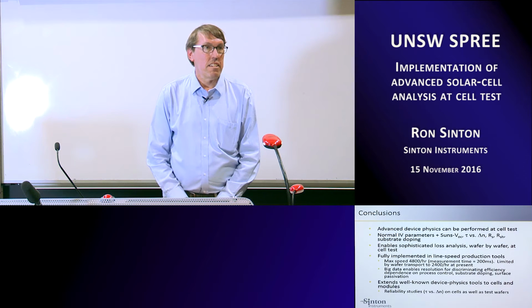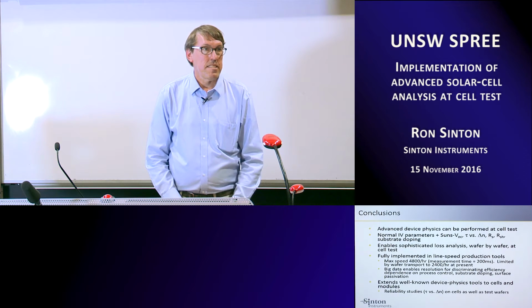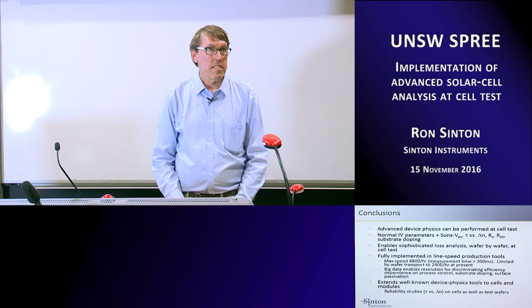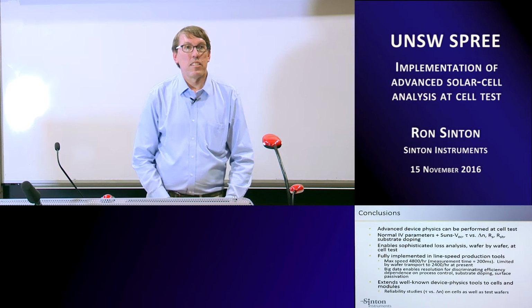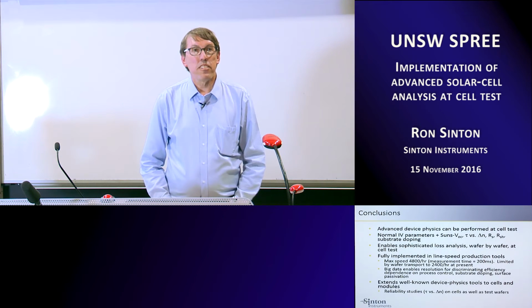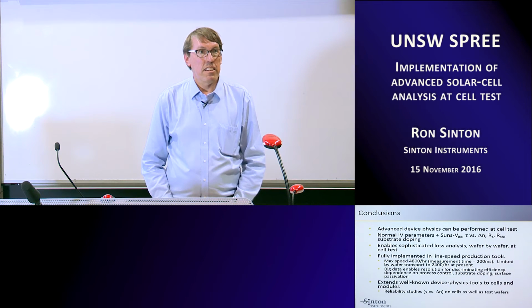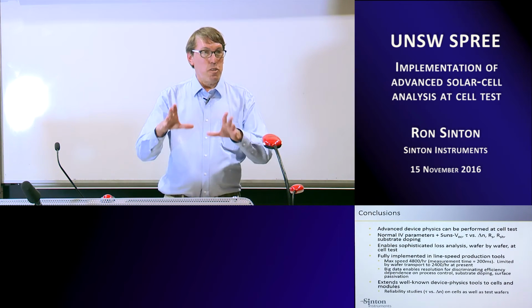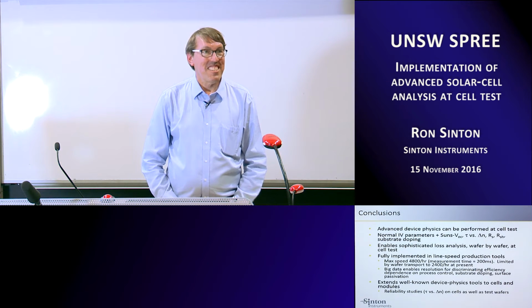For the extraction of the shunt resistance, you said you measure it at the gradient at voltage equals 0. Have you looked at the errors that can arise from having different J0 components, because they'll also have a non-zero component there? Right. Once you get to high efficiency cells, you don't have that. And what we trust the most is an ohm meter measurement, which is to put 1 milliamp across a big cell and see what the voltage is in the dark.